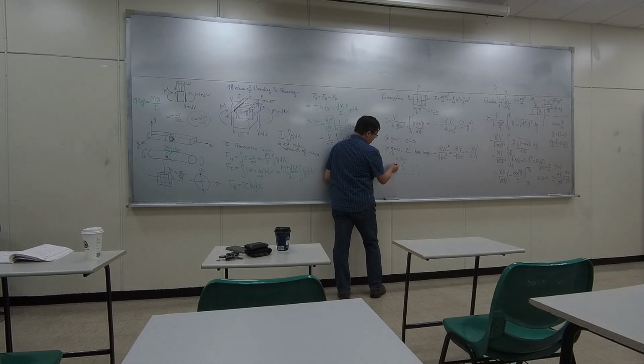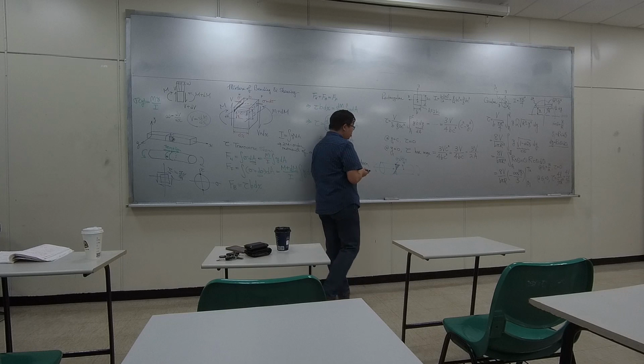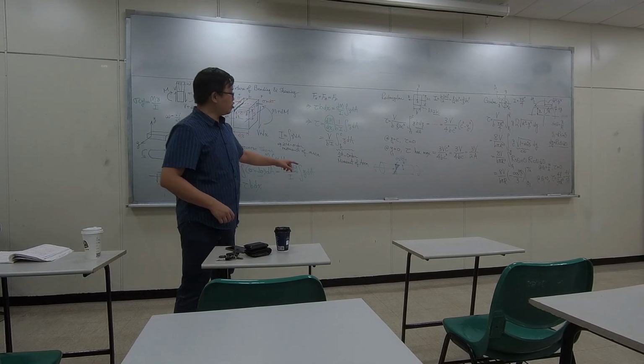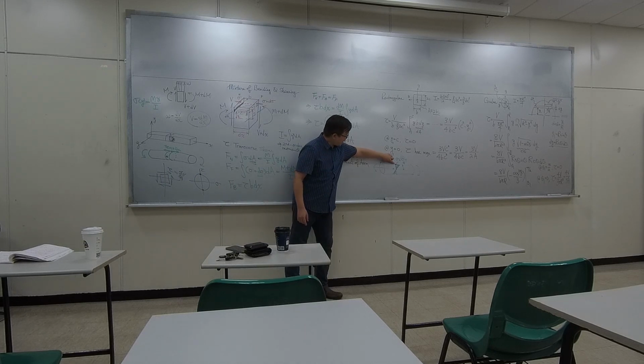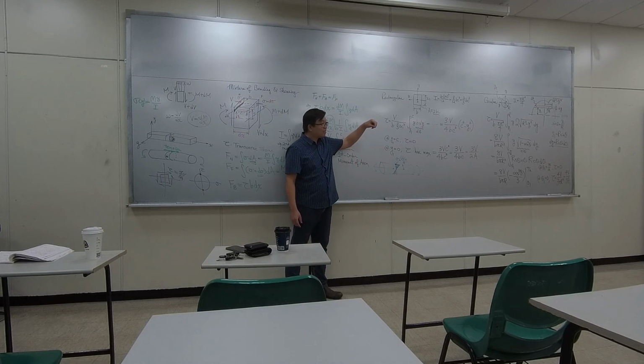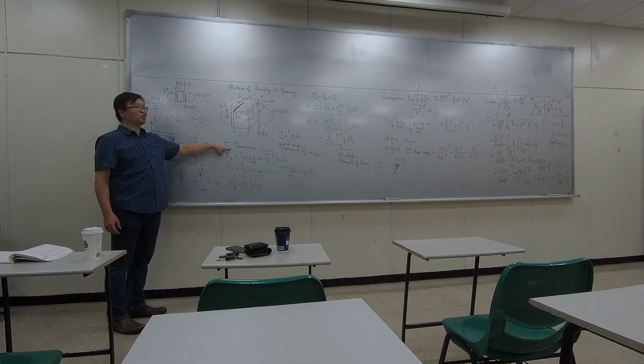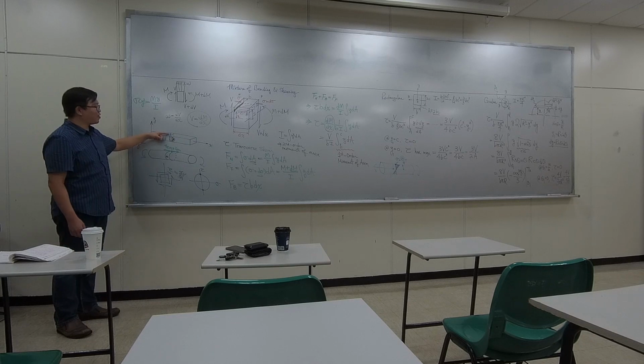But you can have stress at any position. However, if you are standing in the middle, the radius is 0. That's why in the middle, no normal stress, only from the edge. So usually when we are dealing with bending problems, we care about the point on the very top. And usually when we do that, we don't need to care about transverse shear, because transverse shear at the very top is 0.